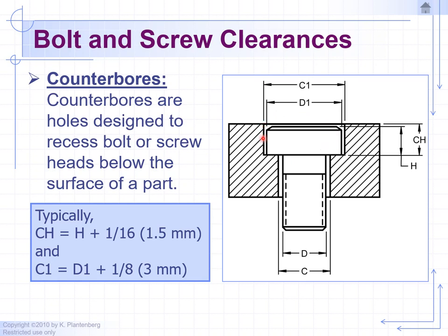So what size hole do we use for the head? Obviously it's a clearance hole. The hole will always be larger than the head. And again, you're going to be able to stick a credit card or something thicker between the head of the bolt and the hole. So what size hole do we drill for the head? So here's the formula.